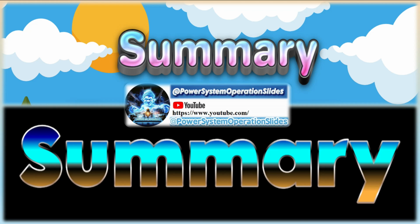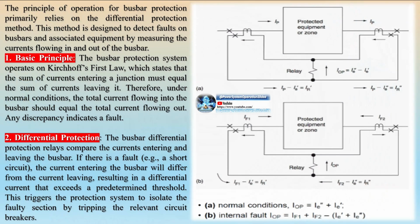Busbar differential protection configuration: centralized arrangement. Numerical centralized busbar protection is common in new substations and in retrofitted older substations where the existing cables are still in good condition. In this setup, the amount of cabling is similar to that in conventional arrangements. Cabling reduction is possible only if additional protection functions, such as busbar and circuit breaker failure protection, are integrated into the busbar protection relay. The benefits of numerical protection equipment include easy functionality adaptation and simple I/O arrangements. Additionally, numerical techniques facilitate quick and easy connections with substation automation systems, enabling rapid fault analysis and monitoring.